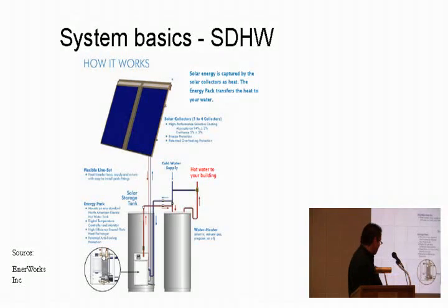So it contains the pump, heat exchanger, and a number of other components, and at the top of it actually has the electronic controller. So what that does is it takes the fluid from the collectors, goes through the heat exchanger, transfers the energy into this solar storage tank, where it's stored, so that's full of water.